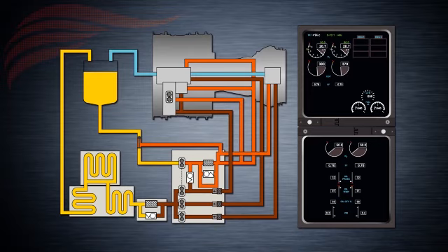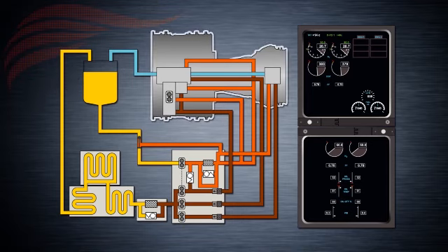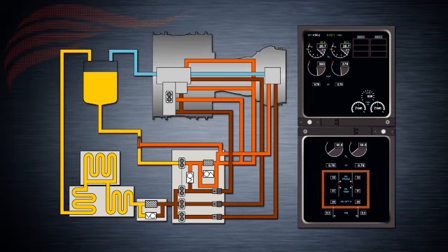The 737NG oil system is divided into three main areas: oil storage, oil distribution, and oil indication. The oil storage system is in charge of making sure the oil is continuously supplied to both engines. There's an oil tank in the oil storage system that holds engine oil and allows oil level checks to be done. The engine oil tanks can each hold roughly 20 liters of oil.